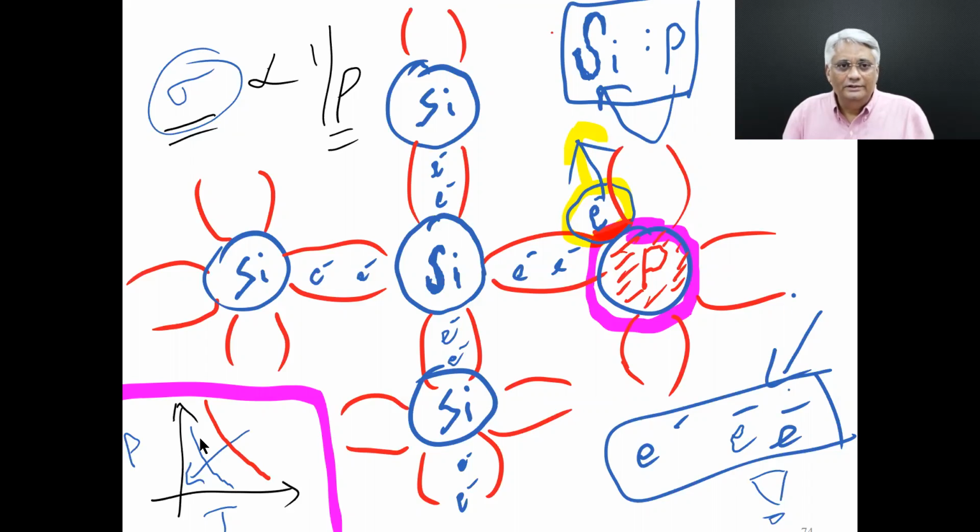This clearly shows that there is a significant change in conductivity, but what is the extent of additional carriers that you're bringing into the lattice? That can only be determined by experiments like the Hall effect. Hall effect measurements will also give you information about the type of the charge carriers, whether you're dealing with electrons as majority charge carriers or holes as majority charge carriers.